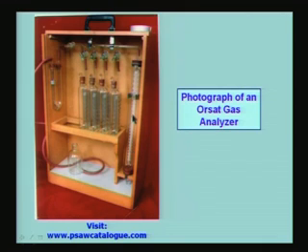What is done is a sample of the gas whose composition we want to measure is taken in the burette, and then it is communicated with each one of these reagents in turn, and then it is brought back into the burette and the volume change is measured.